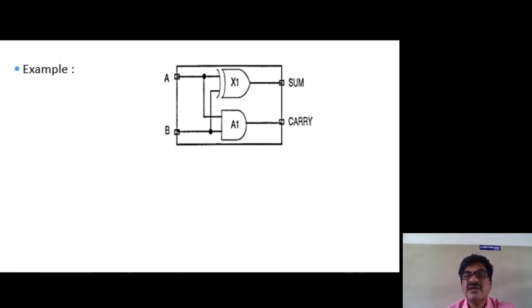So this is the half adder block diagram. For writing the entity for any digital circuit, there is no need to know the internal logic. Internal logic means whatever gates it has and the connections between them. No need of that information. Only how many inputs that digital circuit has, and similarly how many outputs it has. That information is enough for writing the entity.